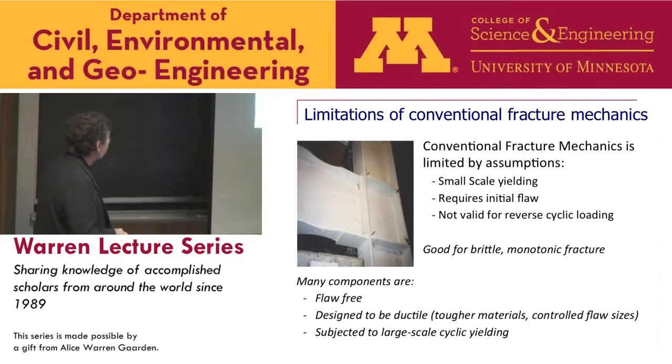So the thing is, after Northridge, when we started to use tougher materials and we were careful about our details, we got rid of the flaws or minimized them, and used higher toughness materials. So then the question is, well, what sort of models can simulate fracture under those conditions? So it's more of a ductile fracture in a continuum. So that's really the genesis of the work I got into about 10 or 15 years ago now, working on these ductile fracture models.